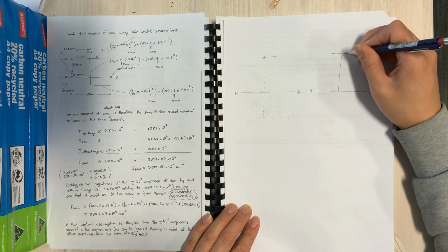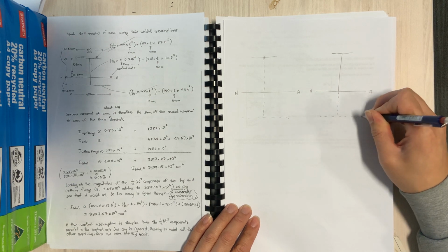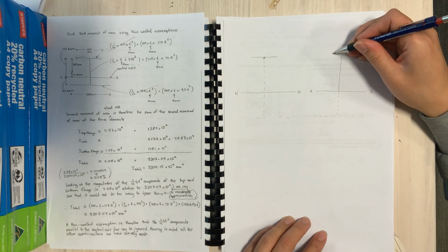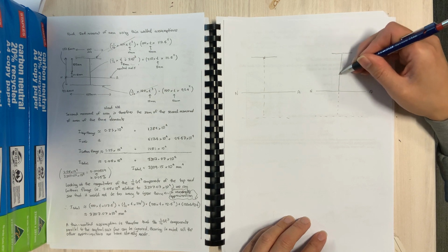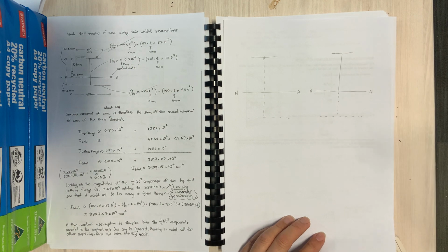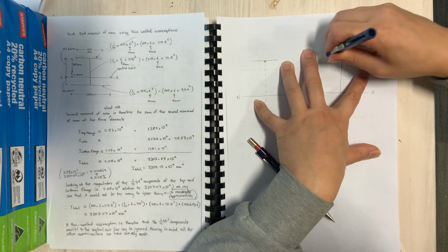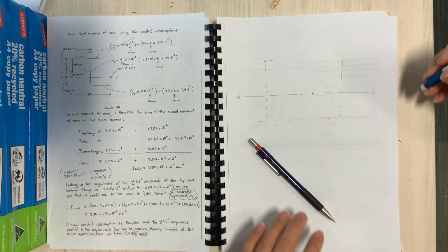Okay, so down to the neutral axis, and then we've already subtracted it from there. So we'll be working out the first moment of area of that section about the neutral axis, and then dividing it by I. But there's an easier way. The easier way is just to work out what that bit would be.